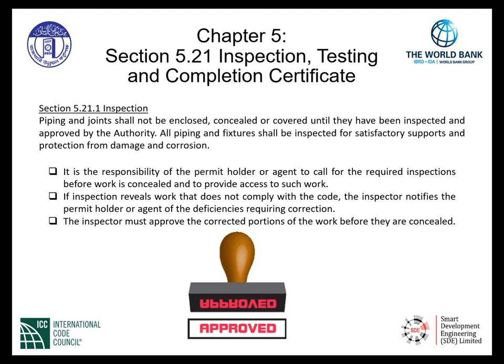This is important so we can verify the materials that have been used are proper, that the materials have been approved and are in this code. The fittings have been made up according to proper installation standards, the correct size of pipes according to the construction documents is what we look for out in the field, and the bedding as well as the depth of the pipe accordingly.